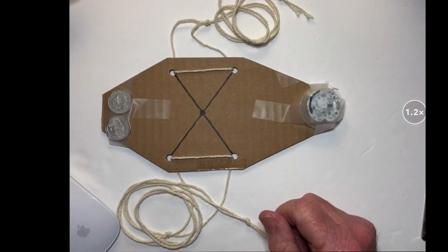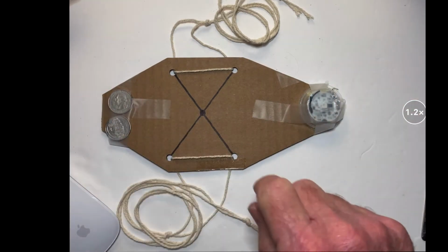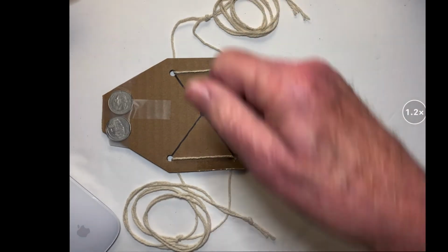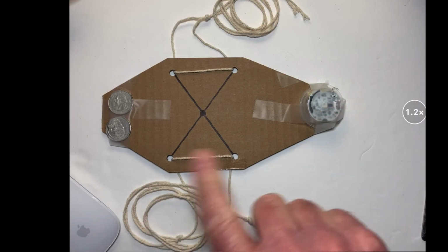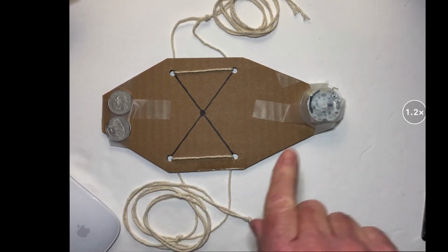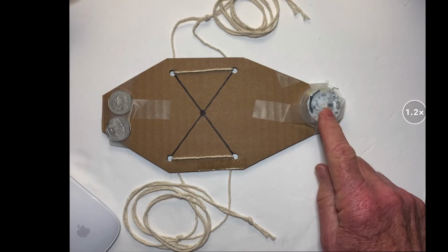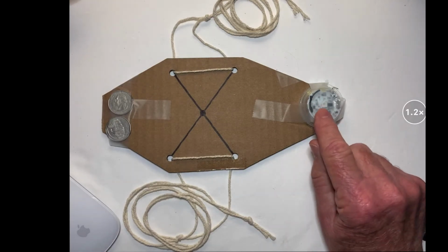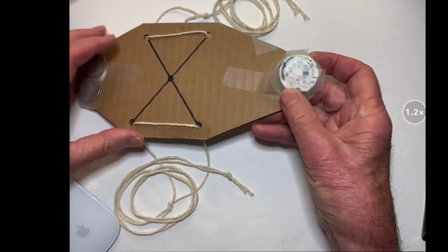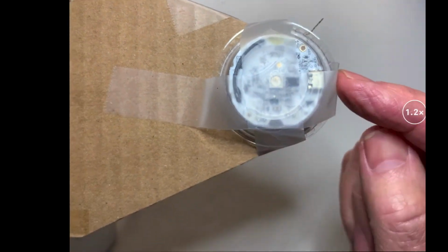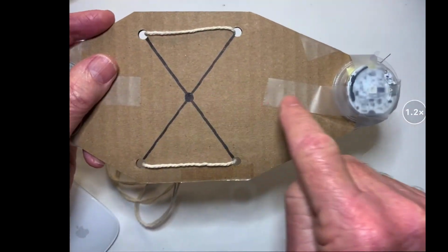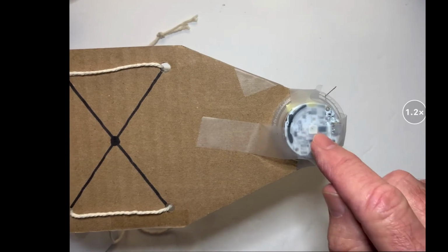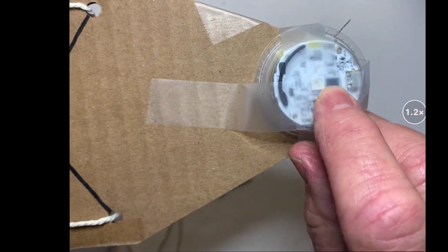Here's the centrifuge you're going to use to spin the sensor in a circle. 2 loops of string, one to hold in your hand, one to wrap around your foot, so you can string this out and hold it in tension, wind up the string, and let the string unwind to spin it around in a very nice controlled way. IMU sitting in the sensor board here, counterweights here to make this thing spin in a balanced sort of way. We want to make sure you mount this board here with the USB port directly on a line perpendicular to the axis of rotation. So here's the Bluetooth antenna, here's the USB port. The IMU is the little black dot right there. That's where we're going to measure to.